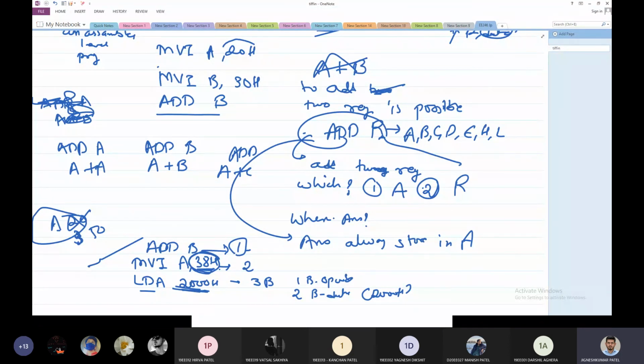See, now one more thing. Whenever there is an instruction, it has an opcode, and the opcode is always fetched. That's the first point. So whenever anyone asks you a question like what would be the first cycle, always say opcode fetch. You will always be correct. Because 8085 must first understand what has to be done. Who is going to tell it what has to be done? Opcode is the way. So first, always the opcode will be fetched. By understanding the opcode, 8085 will know what the next step is. But in the first step, it will always fetch the opcode.